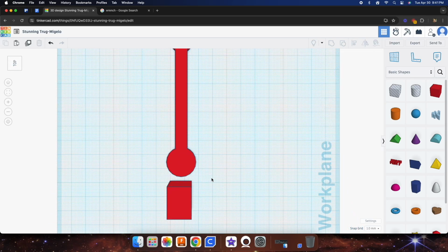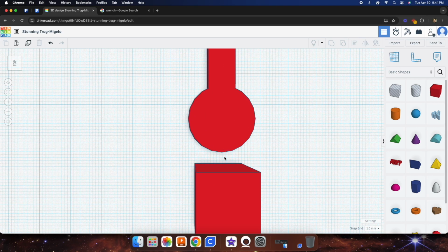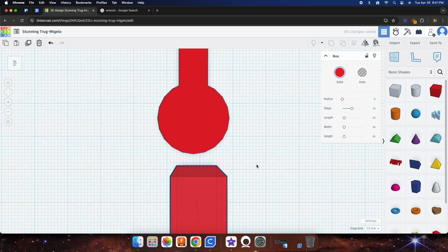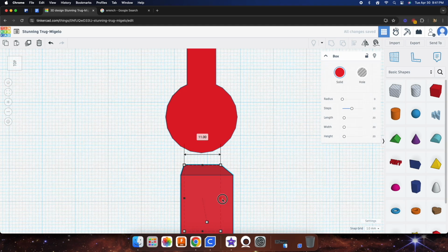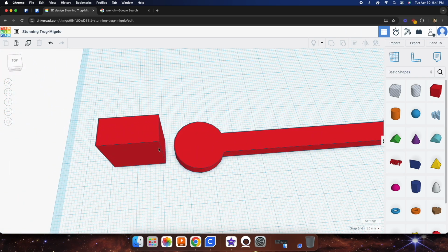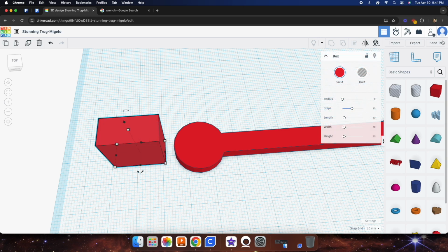So pan, zoom in a little bit. Let's make it 10. There we go. 10 looks pretty good. So I'm going to click this. And so when you click on an object, this box you'll see appears. One of those things, the top thing, is you can click either solid or hole. By default, it's selected as solid.